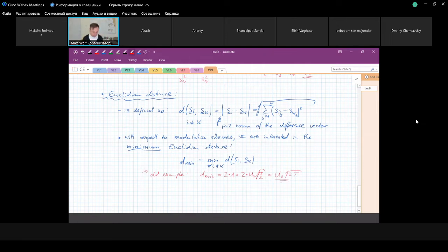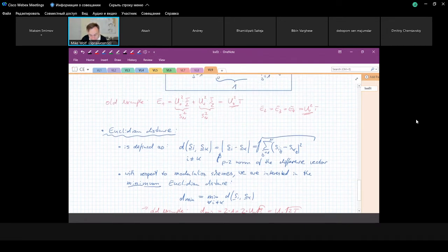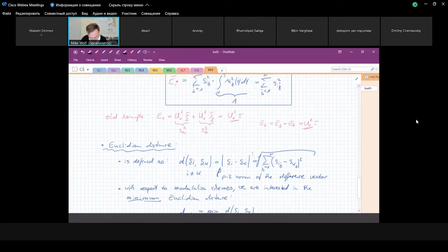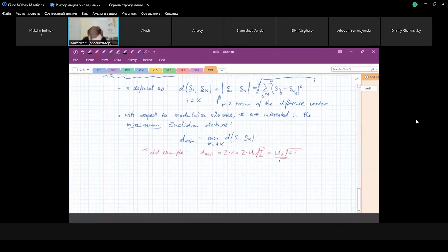Later, if we talk about the characteristics of the modulation schemes, we explain this Euclidean distance as a function of the mean energy between these signals. If we define the mean energy, all signals usually have the same probability.